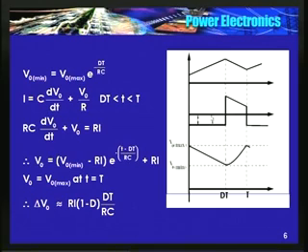That's why capacitor current is finite, and positive. I'll repeat again. Just prior to opening the switch, inductor current is higher than the load current. That's why the capacitor current is positive. At this point I close the switch, immediately the diode turns off, the entire load current is being supplied by the capacitor.